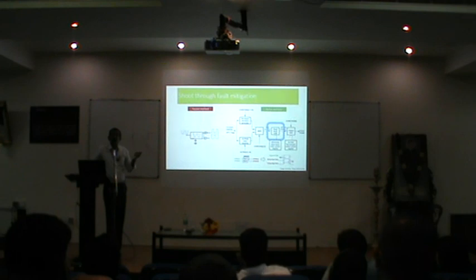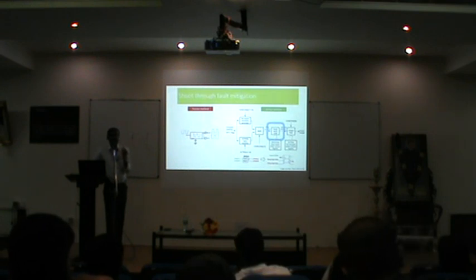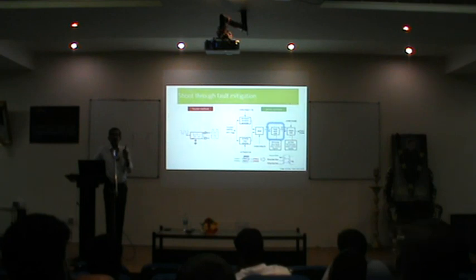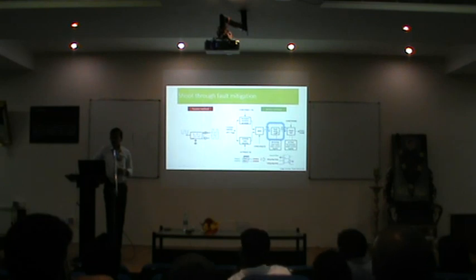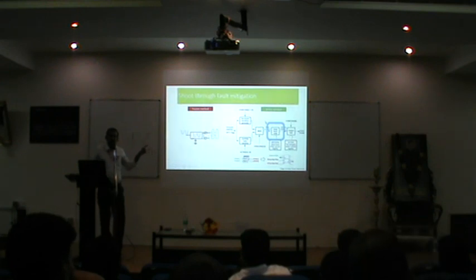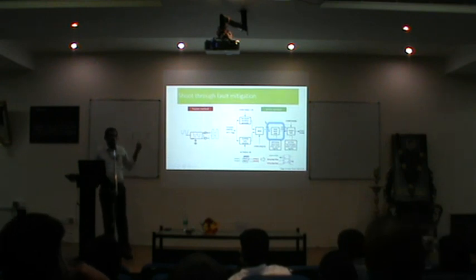We go for circuits which can give us programmable dead times. We need to introduce a deadband time, but this deadband time should be programmable. I should be able to control it without any change in the hardware structure. And that is exactly what you see here as a deadband unit. So your digital controller should have a provision to generate deadbands like this.